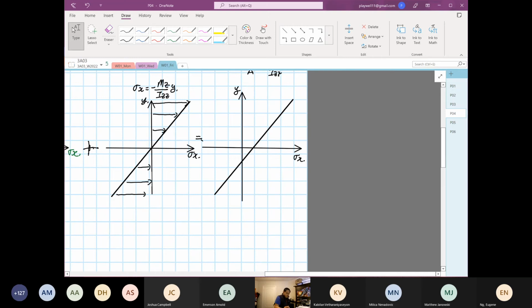What you realize now, if we sketch the normal stress distribution, is this will be tensile, tensile, tensile, and then this will be compression, compression, compression. Now this line over here is still our centroid. No dispute. The position of the neutral axis has been shifted. It shifted to here.